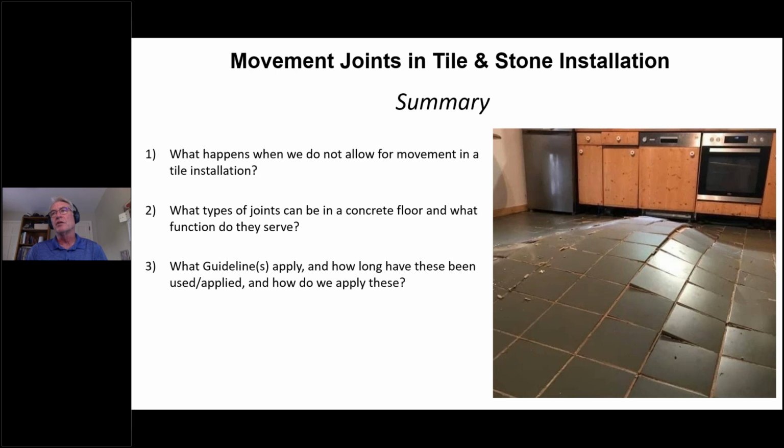All right, here's a good one that I never even thought of. If grouting with a urethane grout, can that be used in the expansion joint area, or do you need to use a different type of caulking? So the material that needs to go into a movement joint has to meet ASTM C920. And I'm not aware of any of those that meet that. So I will say it has to be a different material, a caulking.